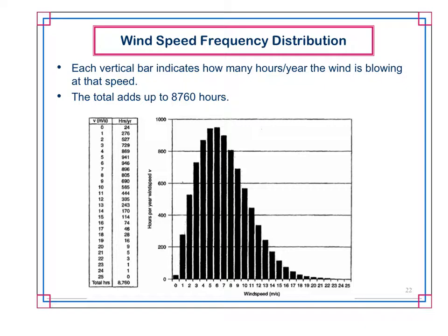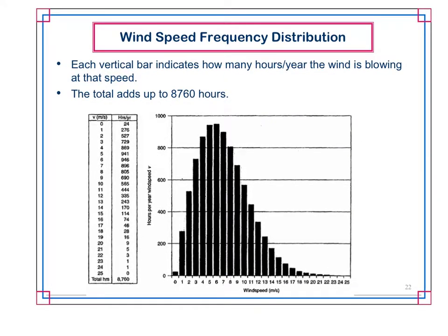So if we can get an anemometer tower and actually get data, then we can say, well, we got no wind speed for 24 hours, or between 0 and, let's say, 0.5, 0.6 meters per second. From 0.5 to 1.5, we had this many hours, and on and on until we get to the point where you're outside any realistic range. 25 meters per second is essentially hurricane winds, and your wind turbines probably wouldn't be running.